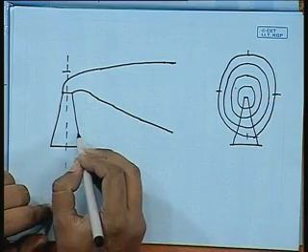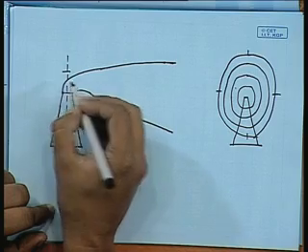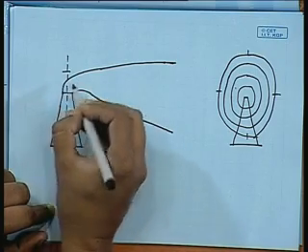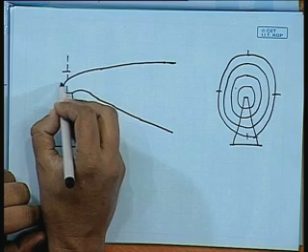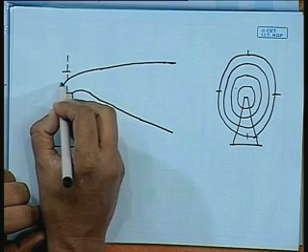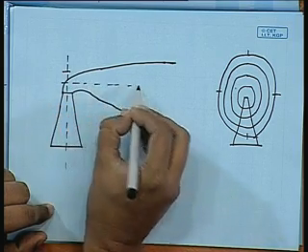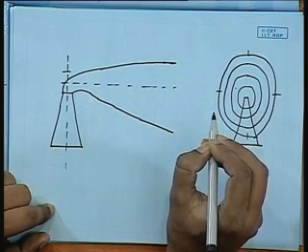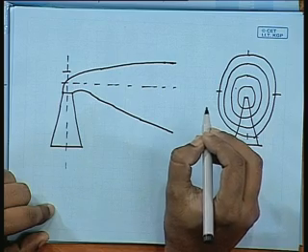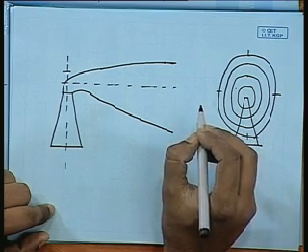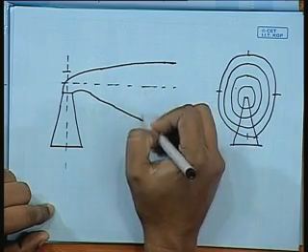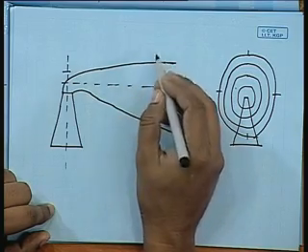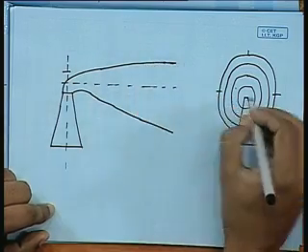One important thing here: for the Gaussian plume, we would understand that this should be forming a center line. It's not necessary that all plumes follow a center line, but for the Gaussian plume distribution we would observe a center line, and this would form a symmetrical distribution on both sides.